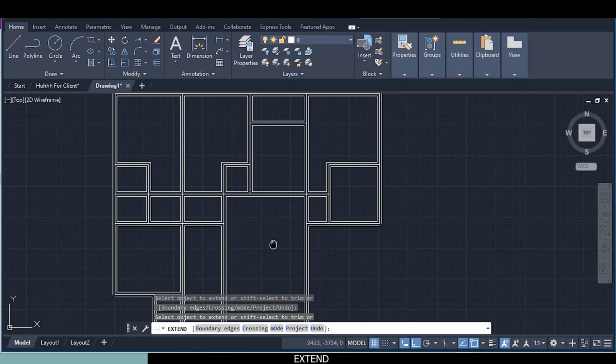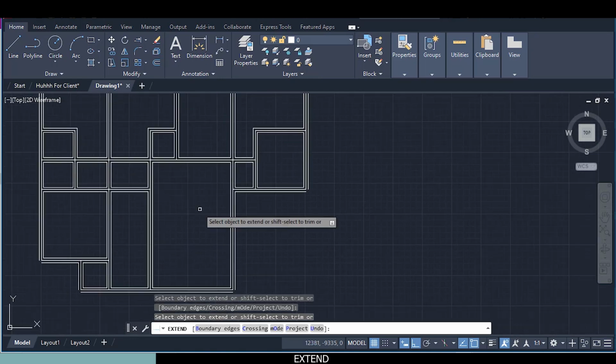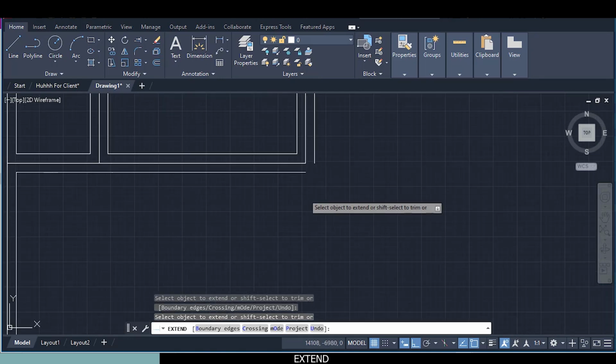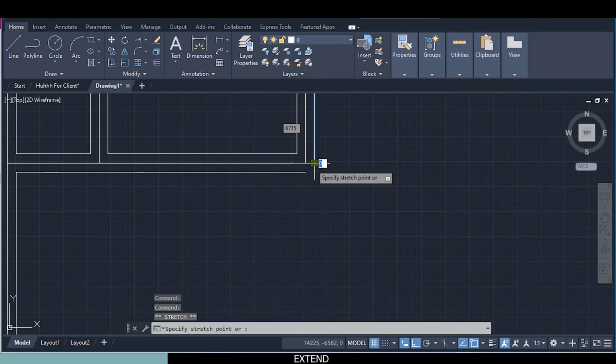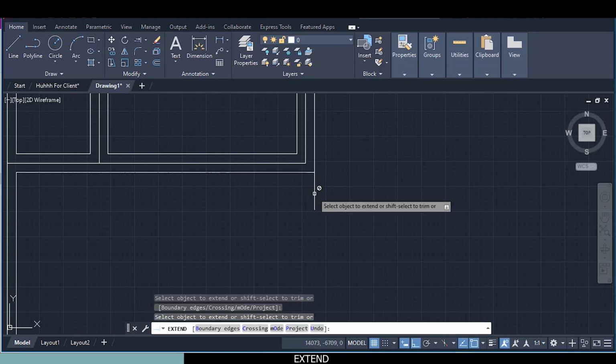I think we are done with the inner ones. Let's finish with this external wall. I will select the line, click on this grip, come down, press escape, extend, click, hold down shift, not erase, trim that.